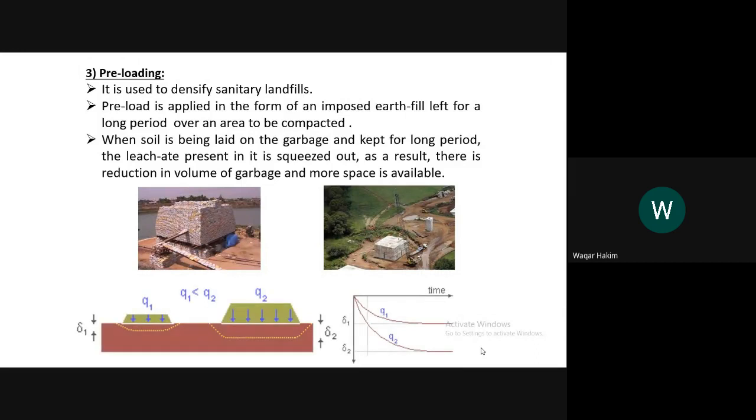Preloading. We use this technique for sanitary landfills and engineering landfills. We apply preloads on soils to improve the bearing capacity of the soils. And we can see in the figures that a surcharge load is applied on the soil, and the settlement-time curves show that Q2 is greater than Q1. So the Q2 curve settlement is more than the Q1 time curve.